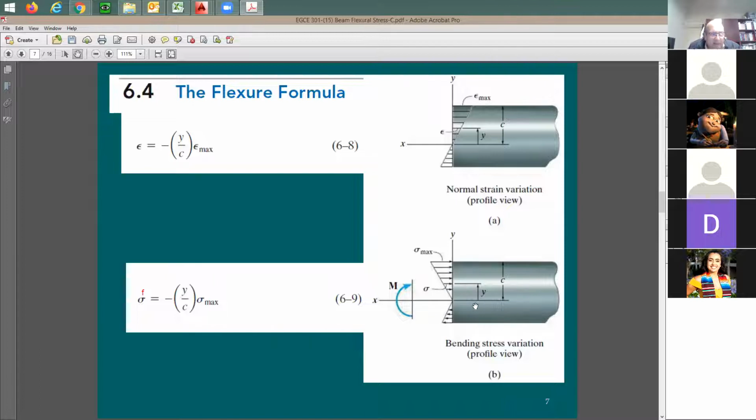The stress at any level at point y measured from the neutral axis is going to be also given by the same equation. And this is a beautiful thing about having a homogeneous section. So everything, I mean, there is no cracking. If you like to consider the concrete to be homogeneous, this is going to be just all the way between the zero stress all the way to the cracking point. So as you see here, we can utilize exactly the same equation. Again, usually c is going to be the depth of the neutral axis, measured from the compression. It's going to be c lowercase.